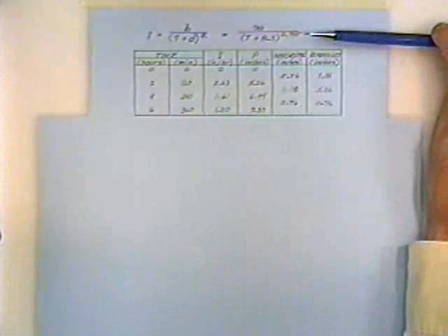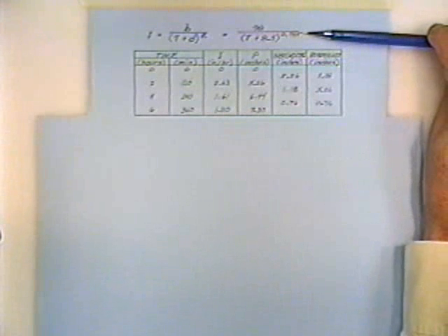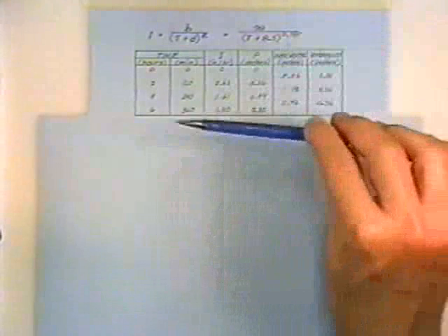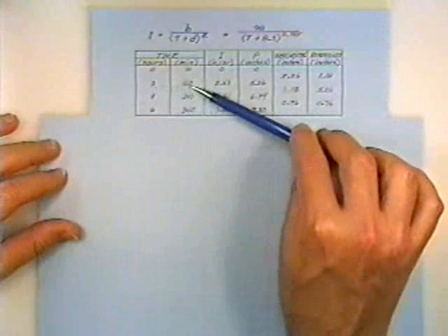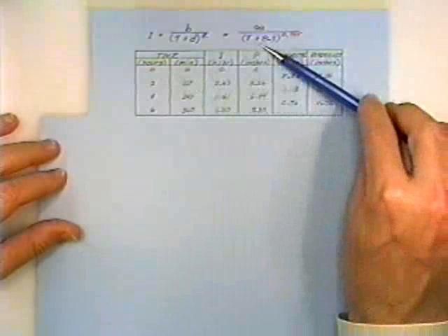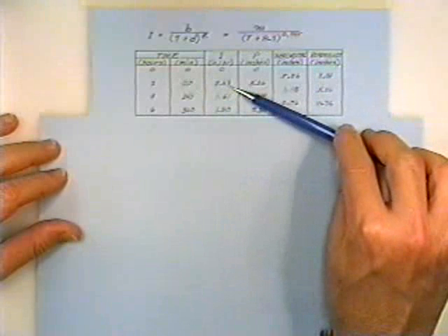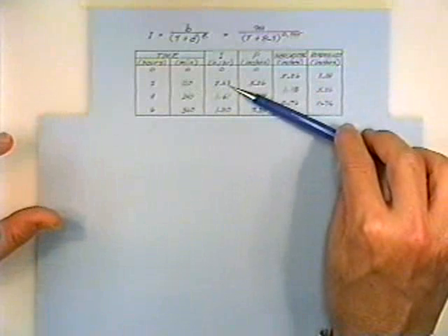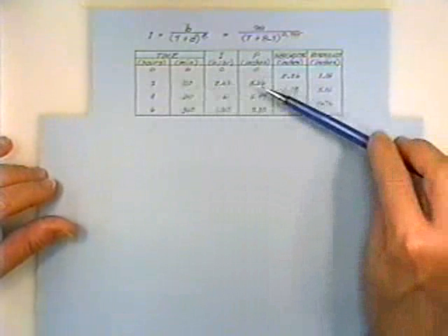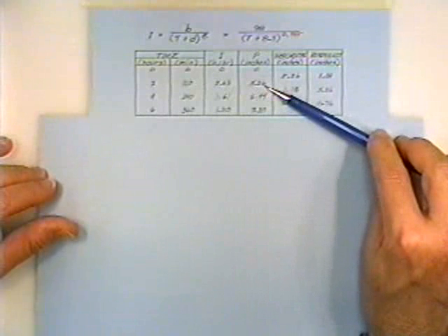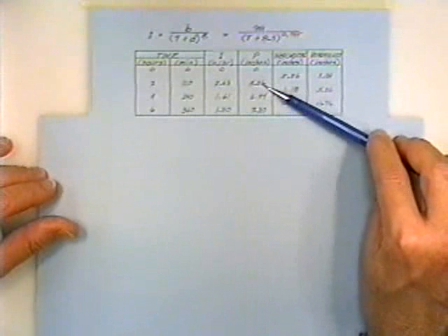We're using the Department of Transportation equation, which we've used already, and we're saying if it rains for 2 hours, that's 120 minutes. We plug into this, and we get 2.63 inches per hour if it rained for 2 hours. Now, if you multiply 2.63 inches per hour times 2 hours, you get 5.26 inches.